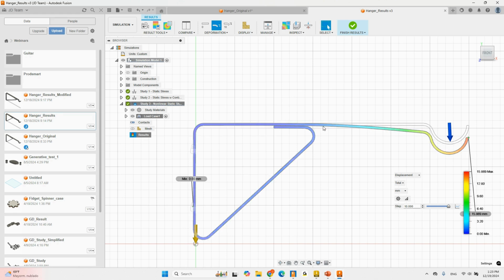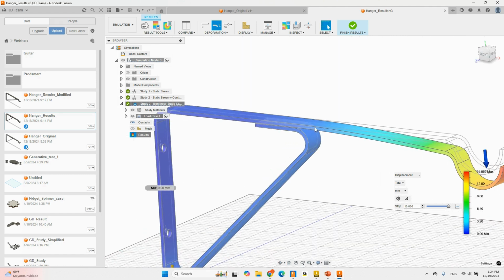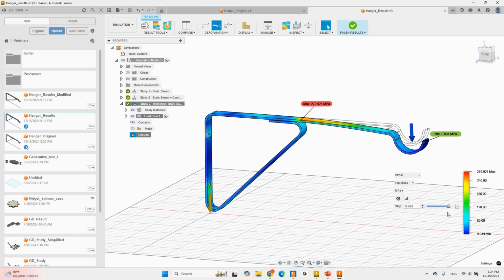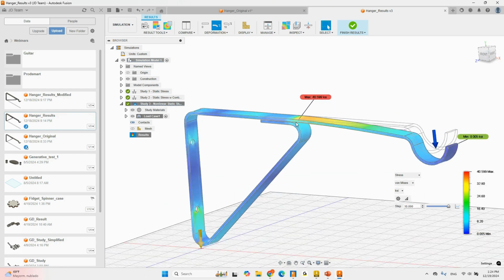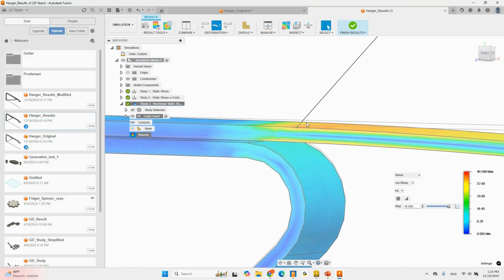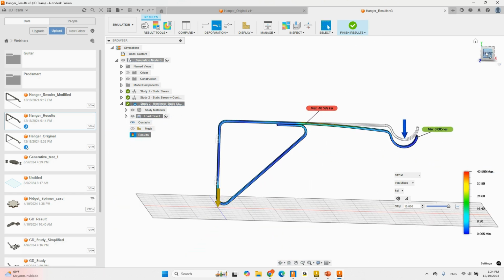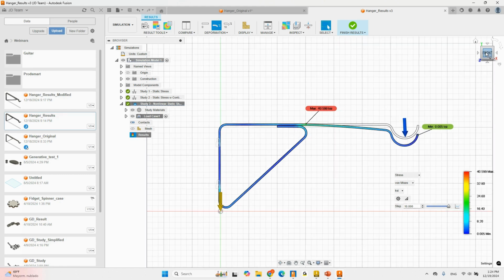But now we know for sure that the software did some adjustment for this type of analysis, right? Besides that, if I check on the stresses, I will be able to make sure that once I got past my tensile strength, that's my yield point, the analysis I'm getting is right, but it's considering plasticity, okay?